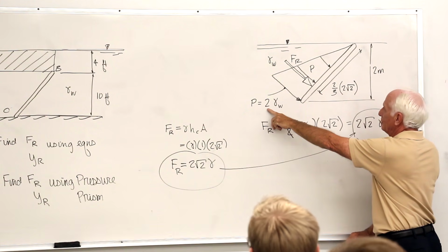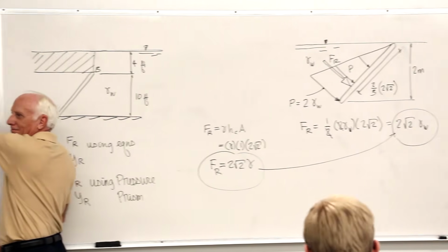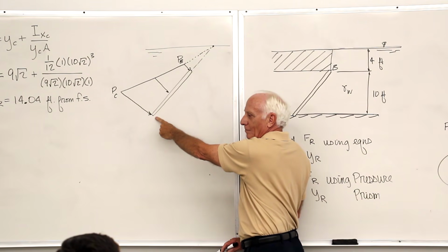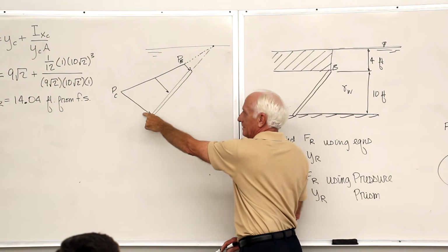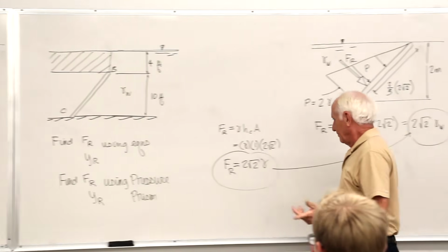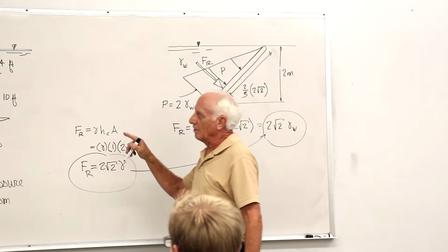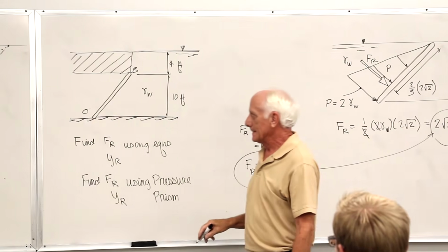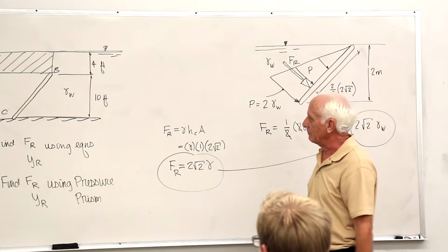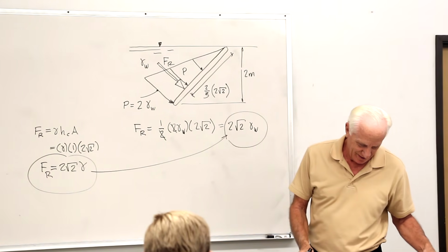Okay, how far down, to what fluid? Water. How far down? Figure it out. What fluid? Water. You know these two pressures. You know this area, 45 degrees. You'll get the same thing. Show me. You get the same answer whether you work it with the pressure prism model or with the equations. This gate's rectangular. It's 1 meter, 1 foot into the blackboard. Okay, so add that to your Monday homework.